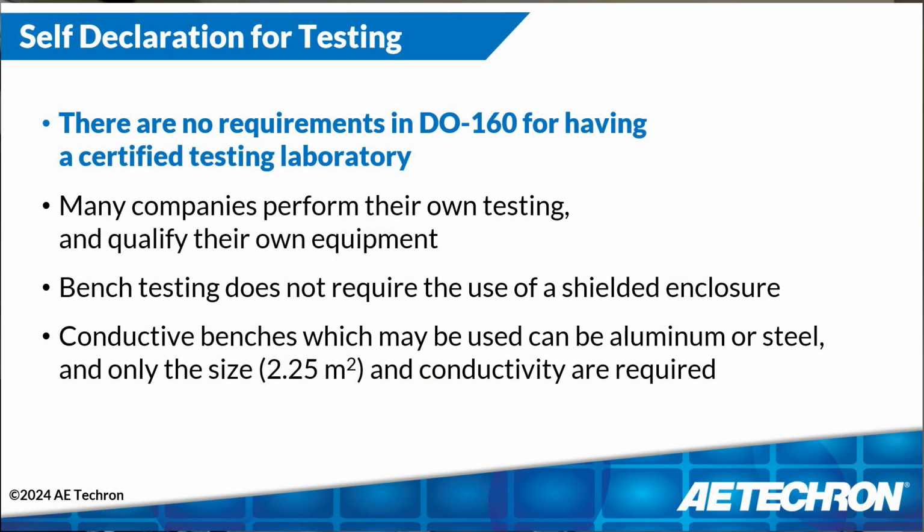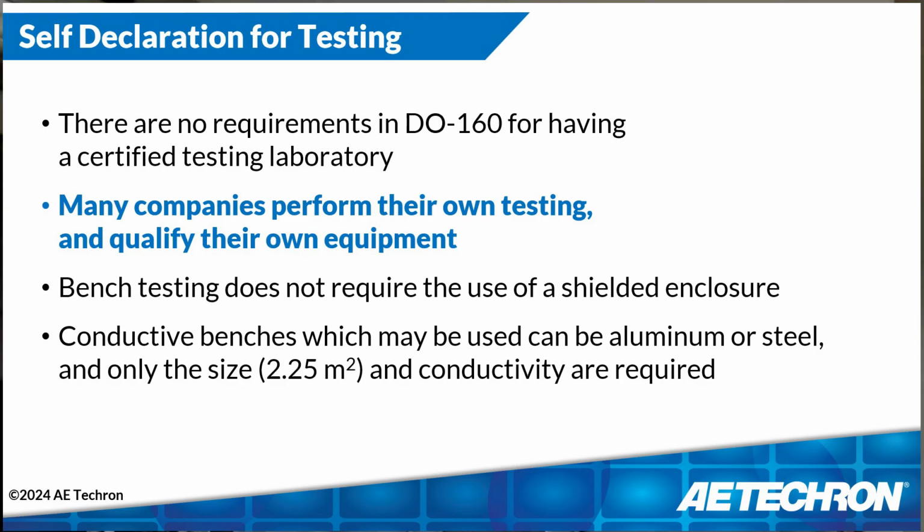The first thing that is important about DO-160 to know is that it is a standard that allows you to self-declare. In other words, you can perform all of your own testing at your own facility. You don't need to go to a certified testing laboratory or have accredited testing performed. This makes the ability to do testing in-house very valuable. There are many companies I know who own their own equipment and qualify their own equipment for aircraft use.